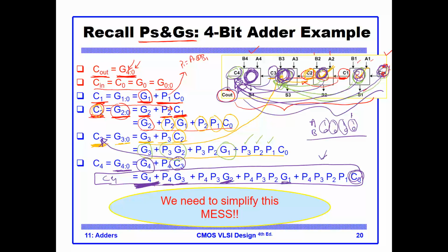So now you can see I'm going to get 0 and a carry, 0 and a carry, 0 and a carry. I'm propagating all the way until I get a carry out of a 1. So what happened? I propagated the Cn all the way to C out. Okay, and this is the case. And you can think of other cases as you desire.